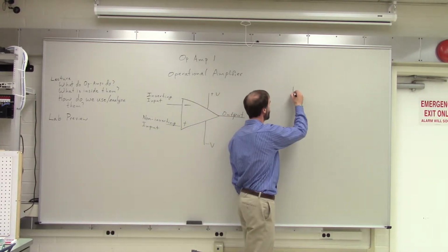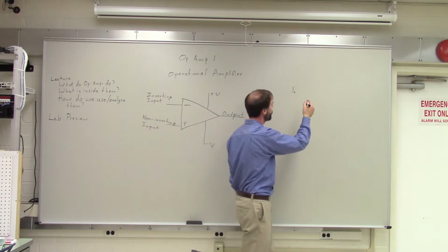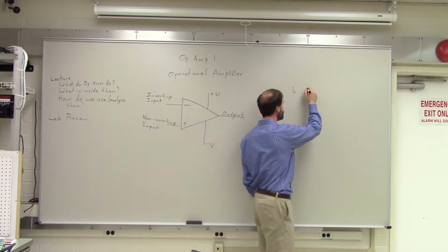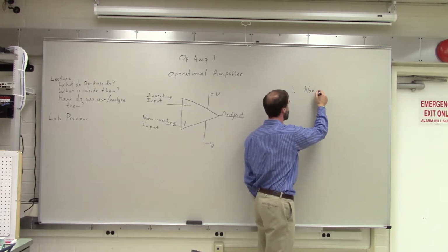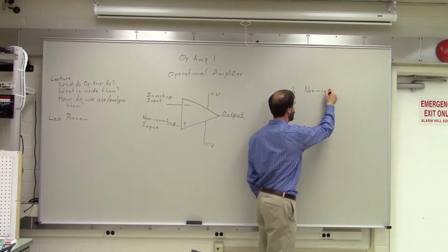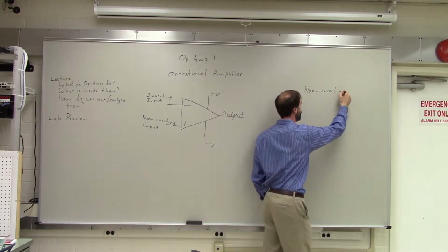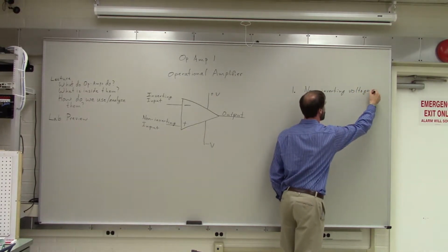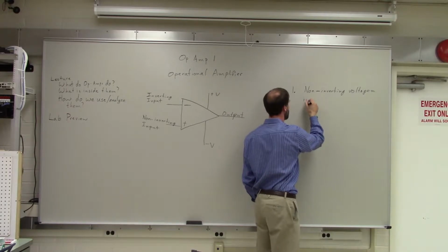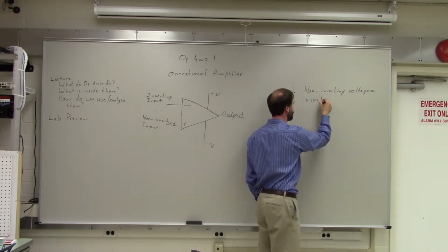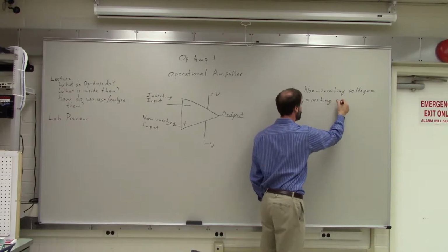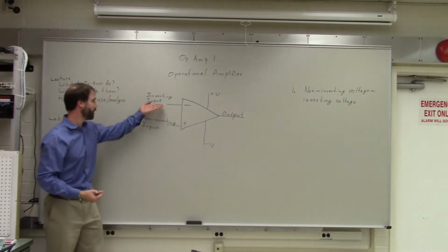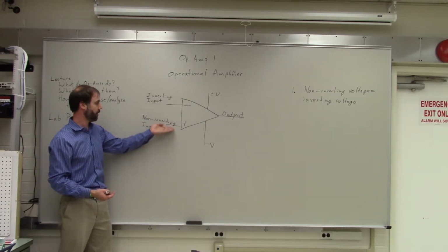The first one is that the non-inverting voltage is equal to the inverting voltage. Basically, the voltage at your two input terminals is the same.